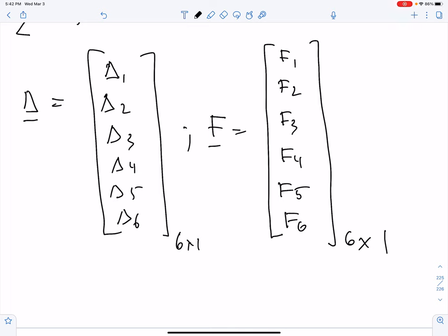As we go forward, you will see the benefit of doing a very careful job going through trusses first, because a lot of the concepts will carry over. It's just the quantities we're familiar with in the case of truss will have an expanded definition. So rather than a force vector, we have a generalized force vector that includes moments, and rather than a displacement vector, we have a generalized displacement that includes rotations.